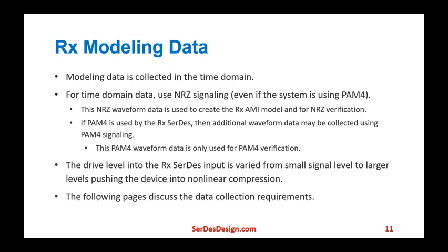If PAM4 is used by the receiver SerDes, then additional waveform data may be collected using PAM4. This PAM4 wave data is only used for PAM4 verification. The drive level into the receive SerDes input is varied from small signal to larger levels, pushing the device into nonlinear compression. The following pages discuss the data collection requirements.